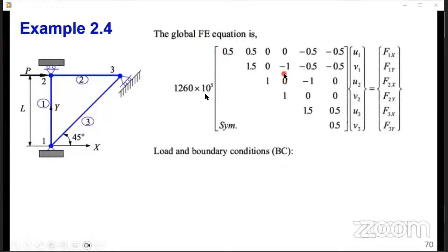one of the things that you have to notice is that our stiffness matrices, as we always say, are symmetrical. If you take the main diagonal, the quantities above the main diagonal are the same. So in this case, we have just written the quantities on one side of the diagonal and then written "symmetry". But for a student, I don't want to be this lazy.